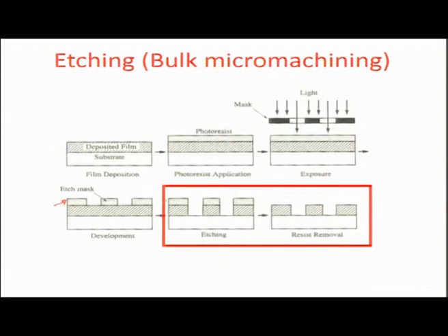So, typically with this kind of resist, this is sort of a step which shows how resist acts as a sacrificial material. This is, let us say, an etched top film which you want to expose. So, you have used resist as a sacrificial material and selectively taken off with etchants the hatched area, so that it can open windows for the base material which can be further etched. Okay. So, the resist is typically removed, and then the sacrificial material here is used as a way of etching out the main material. Okay. And then you can even remove the sacrificial layer off. So, that is how bulk micro machining is typically performed with resists and with patterning on surfaces.